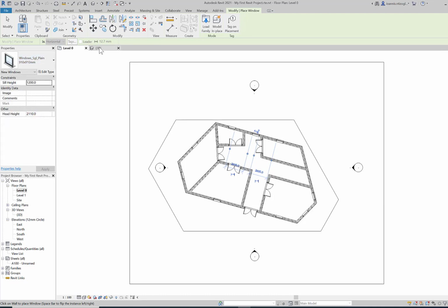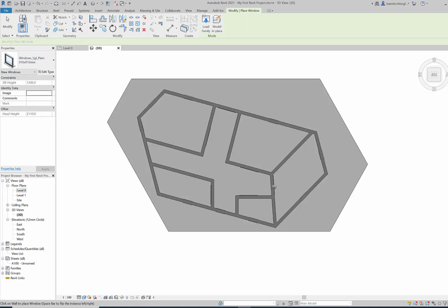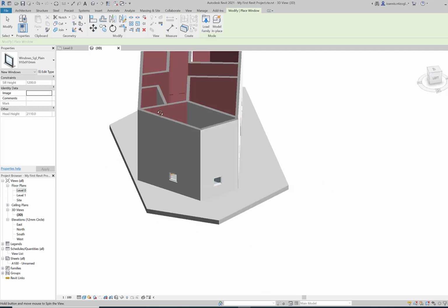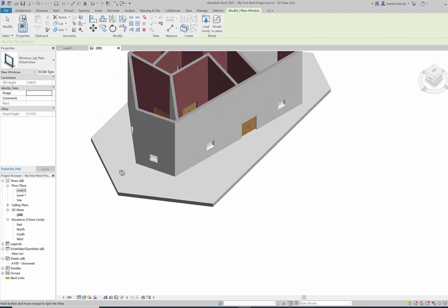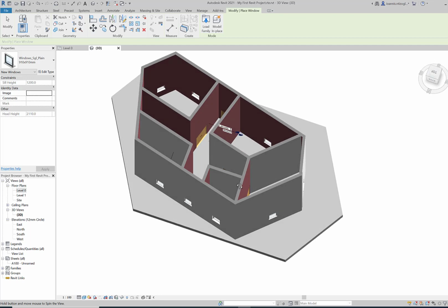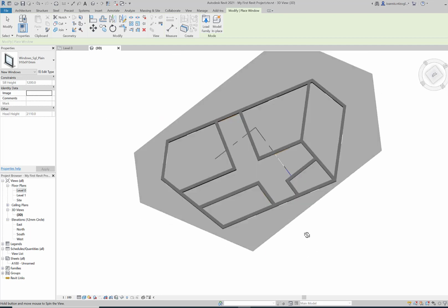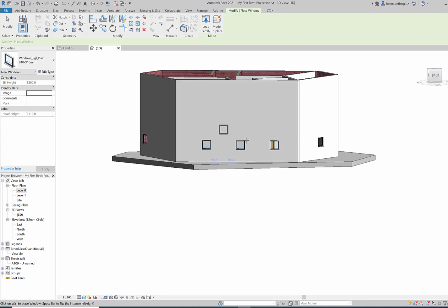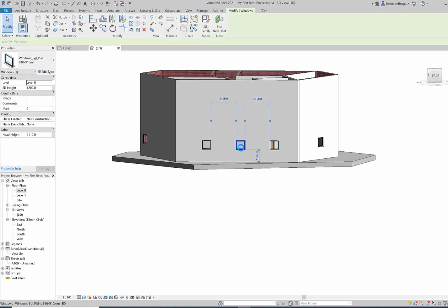If I go to the 3D view, click on the 3D view and hold the shift key down while I right click and drag, I will then be able to basically see the doors inside the house, and basically the hallway. So if the customer says I would like the window to go a bit higher up or lower down, I can use the modify tool, or by using the arrow keys, you will be able to basically reposition your tools. So you click and drag.